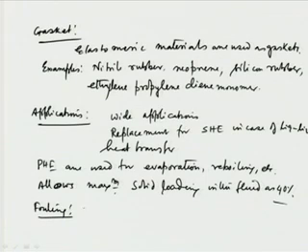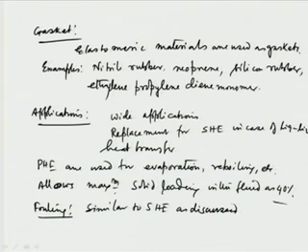Fouling is similar to shell and tube heat exchanger, as discussed in lecture 2. We have discussed already how the fouling takes place, and it is by depositions, by various methods. In addition to that, there will be corrosion also, which is also an important phenomenon. So in this case the fouling will be relatively less, because, as we have seen, relatively costly materials of construction are being used, and therefore the fouling is relatively less.